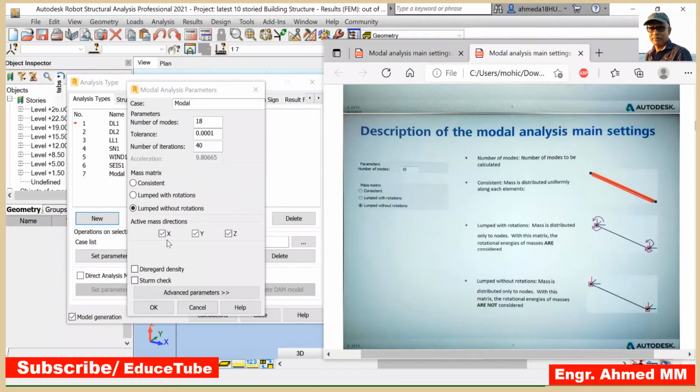Because when a lumped mass matrix is used, a portion of the structure's mass is allocated to the supports and therefore not taken into account for seismic calculation. For these two cases, it is a very important point. Okay, now let's move to these active mass directions.